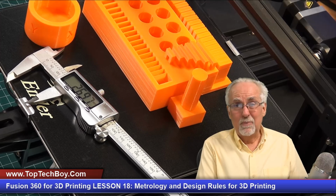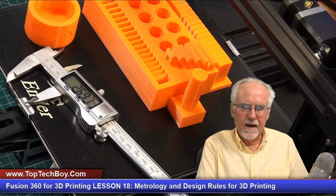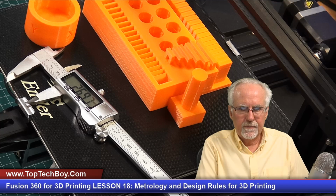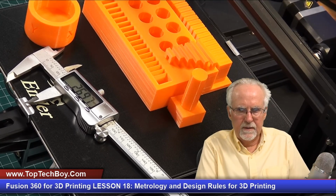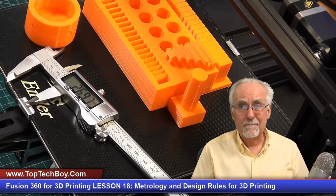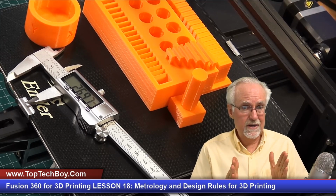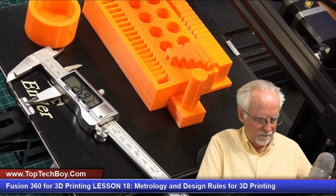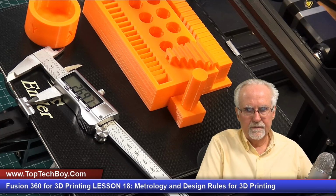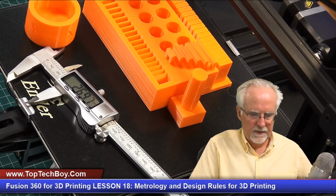And I don't think that's plus or minus 0.1 millimeter. I think it's less than expected. And maybe up here I should put more than expected. A lot of times in engineering, you see people put plus or minus. I don't think this is a plus or minus number. I think the x-axis is always printing a little bit wide, and the y-axis is always printing a little bit wide. So I'm going to put here more than expected, because this will help me later when I'm designing things.